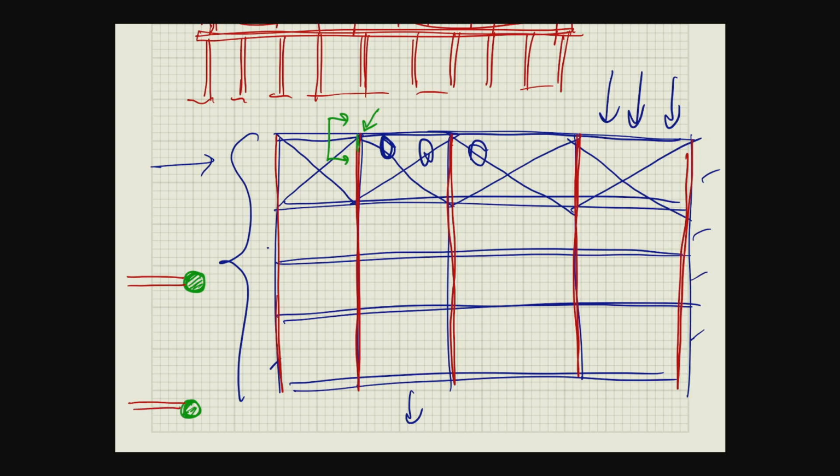Well, the red part must be able to transfer the load, which is going to be from the instability of the top chord. Well, we lock to the bottom chord as well because we need to restrain everything against torsional buckling. So the bottom chord is also locked. Right, and then, okay, well, you can put the details of the...